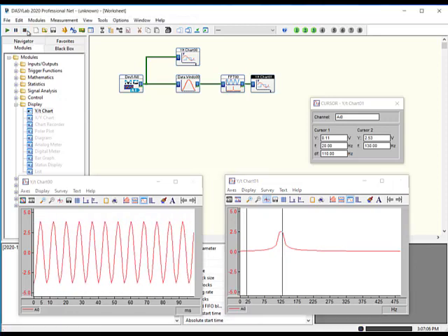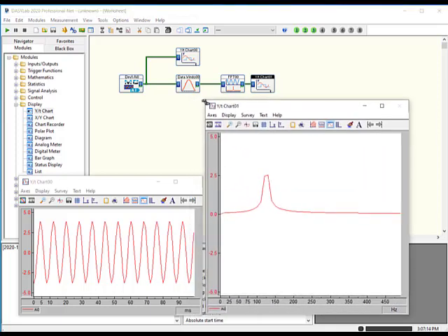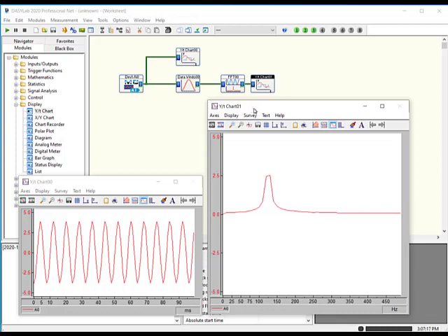Now, when we talk about the FFT, one of the questions that we have is, how do I know what the range and the resolution of the data is? So this is the output of the FFT module. The range of the frequency is based on the Nyquist theorem, and sampling at 1,000 samples per second, DASYLab is going to provide you a computation that is half of that sample rate. So it's actually going to give you 0 to 499 hertz. That's one reason why 500 isn't labeled, because we're only going up to 499.